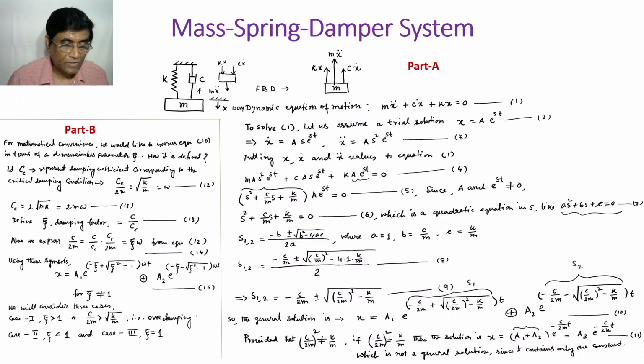Okay, now let us consider two cases. Now you see, very interesting, one thing you should remember: C, M, K, what are they? They are system parameters. M is mass, K is spring stiffness, C is damping constant. And you see, the beauty is that this exponent quantity is always negative, irrespective of what the M, C, K values are. Some students have difficulty understanding that. Whether this is greater than mk or less than mk, it is going to be negative.